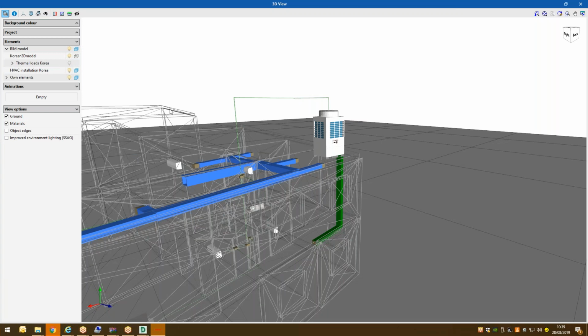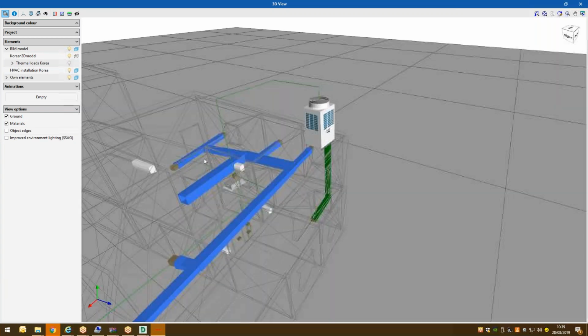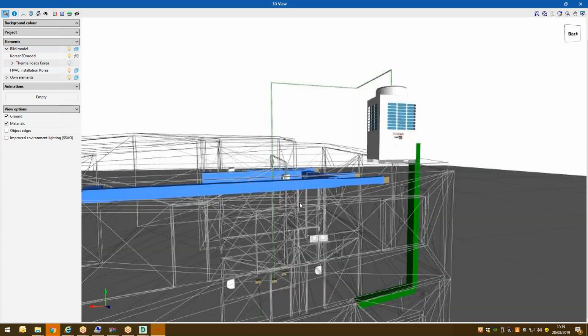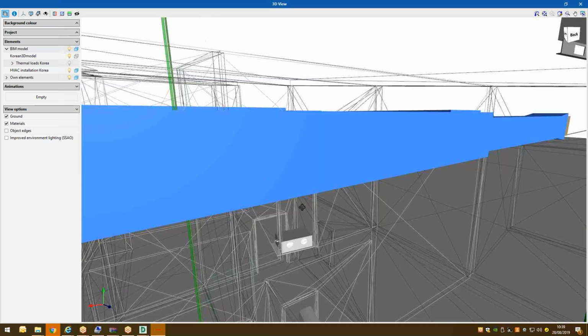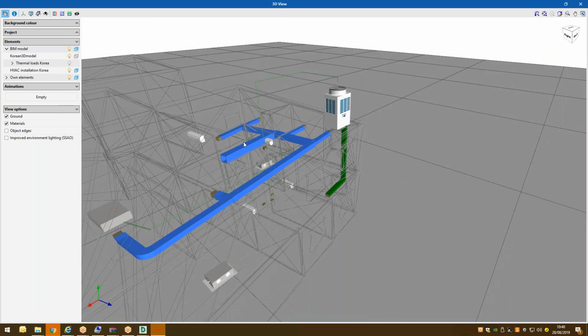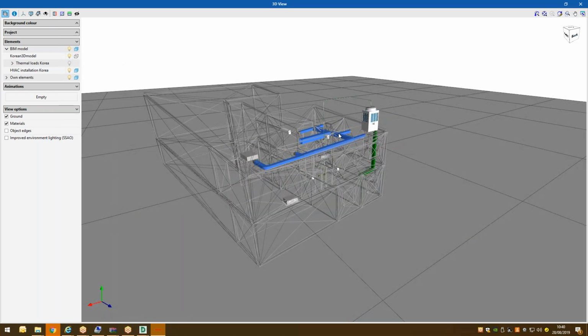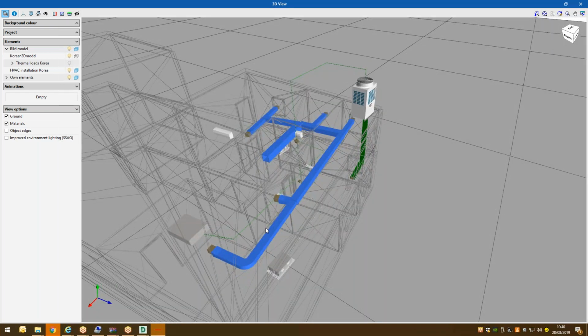If you want to, we can deactivate. Another interesting thing here: apart from calculating and seeing every specialty, we can obviously consult the visual inspection of the clashes. If something of the HVAC installation, for example the ducting sizing, is crashing or overlapping some elements of the BIM elements, or something like that, it's crossing or clashing, we can detect it here.